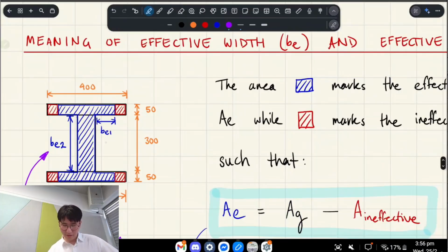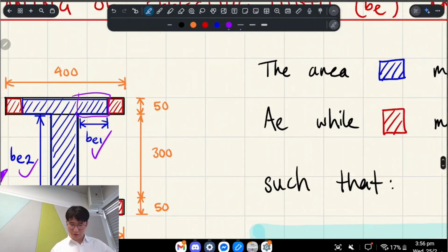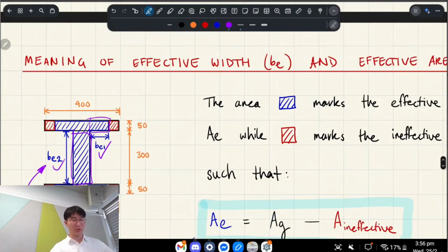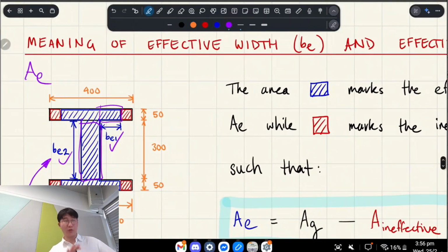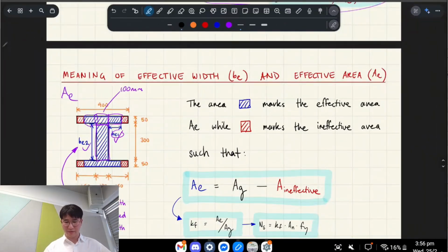So basically, through those formulas, you're going to find BE, right? So we know that that portion is the unsupported portion of that, and that's the unsupported portion of that. And going back to your original point, in the end, we actually want to find AE, right? But here's where you just have to draw it out, and it's a very visual process because you don't want to double count anything. So you want to figure out, okay, that's BE on that side, that's BE, this is the same one, and then we're going to add on that 100 mil again, and then you just add these blue rectangles together. There's not one way to do it because you have to use your engineering judgment to figure out the AE in the end, right?